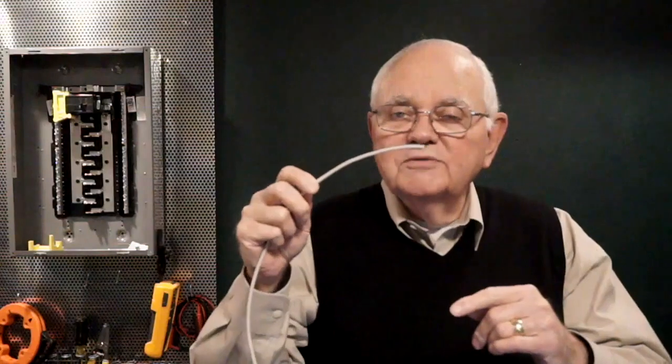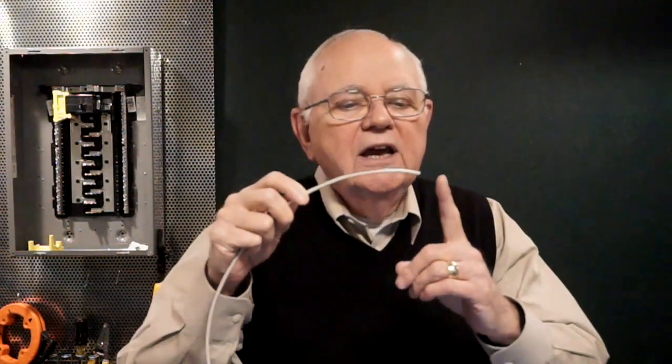Also, keep in mind 110.14(C). It talks about how any chain is only as good as its weakest link, right? Even though this conductor may be rated for 90 degrees C in a dry location, if I pass that 30 amps of current flow and heat that conductor up to 90 degrees C, and it is connected to a terminal that's only rated to 60 degrees C, okay, what have I done? I'm going to overheat my terminal. I don't want to do that. So you need to refer back to 110.14 too when you're actually sizing conductors and determining ampacity values.